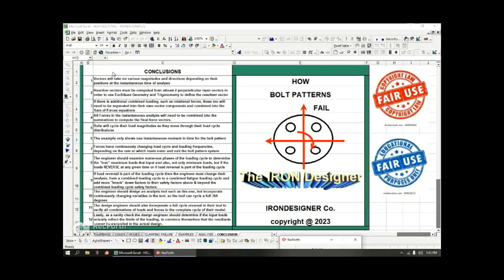So if that pattern was rotating or vibrating or in a reversing condition, you would need to take multiple analyses at each instantaneous point of time in your analysis, okay? So you might have a frequency analysis or a load, peak minimum, peak maximum analysis. You need to somehow decide, is it a static analysis or is it a dynamic analysis?